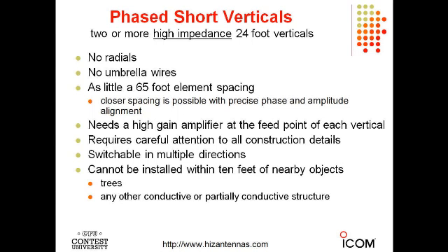Pete, I honestly don't know the detailed answer to that question, but I do know some of the members of our radio club who've installed these high Z arrays and have made the mistake of putting them close to other objects, and they had trouble and contacted the manufacturer, and they said, "Oh, don't do that." It apparently affects the impedance that the preamp sees and some other things. That's exactly what they tell you in the instructions: keep it more than 10 feet away from other objects.